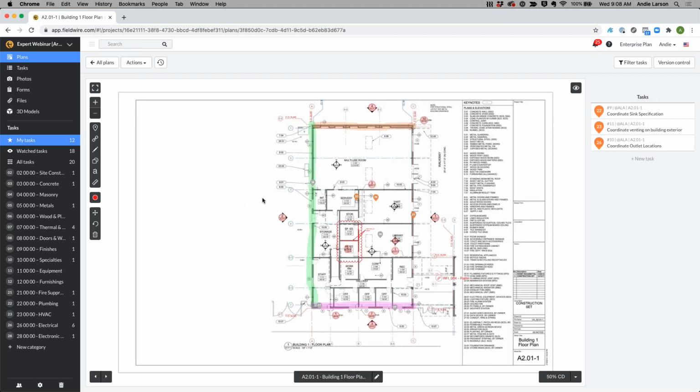The last thing that it'll do with this piece of information of the sheet number is it'll recognize when you upload new sheet numbers. This being said, if you're in the design phases of a project and you have already done 100% DD and now have your 50% CD set, it's going to recognize this drawing number and confirm with you that this is in fact a new version.